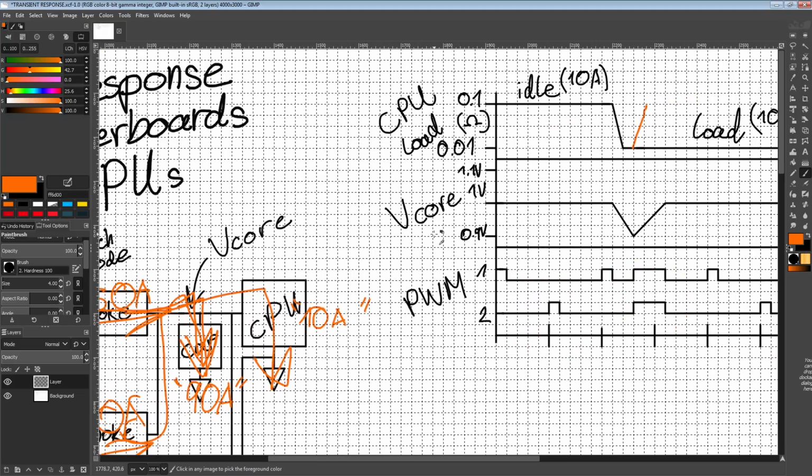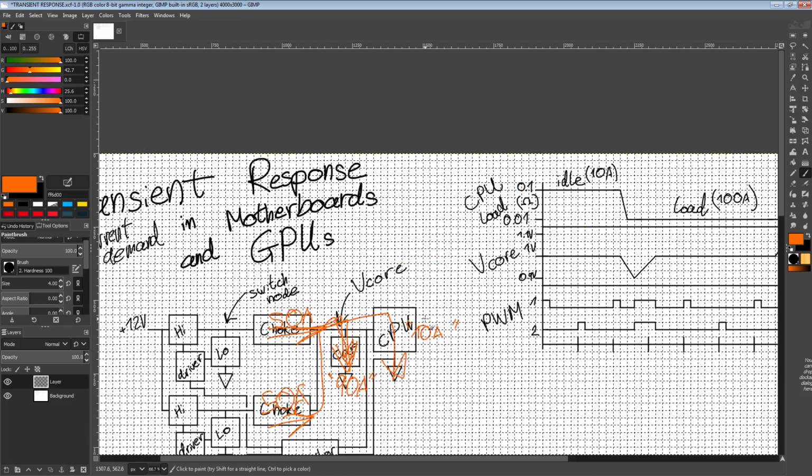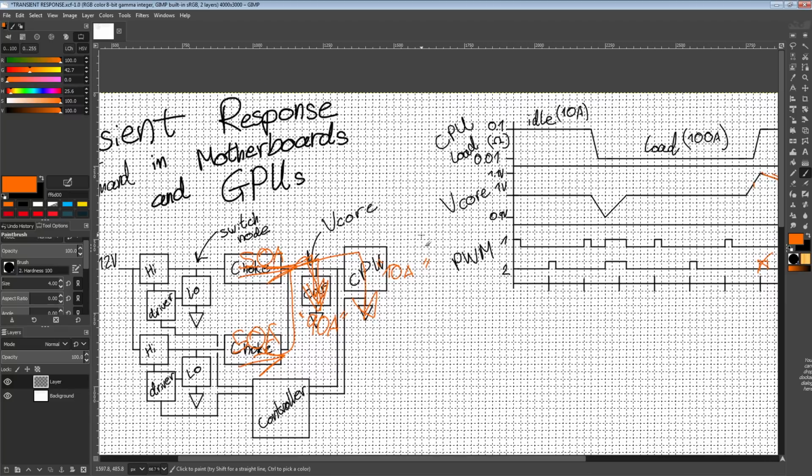So, anyway, hopefully this covers enough information that you can watch the oscilloscope measurement videos I've been doing for motherboards and GPUs and that kind of thing, and they'll actually make sense now. Because basically what we're looking at is the ability of the voltage regulator to maintain output voltage in spite of the fact that the inductors really hate changing output current, like really hate adapting to the changes in the resistance of our CPU, right?